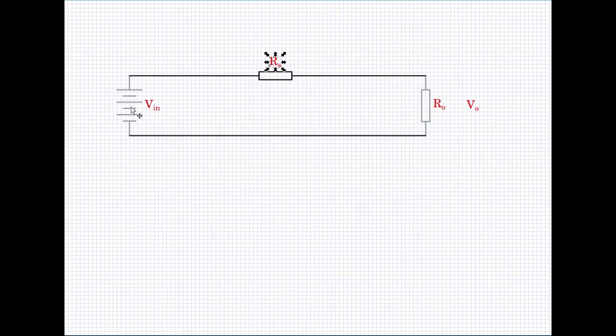Now let us say, for example, we have 48 volts at the input and we need 5 volts at the output here. The remaining 43 volts has to drop across this resistor. This would be the series drop resistor, and this is the typical concept that is used in almost all linear regulators. Now this resistor can be a varying resistor so that you can achieve regulation. As the input voltage varies, you vary this resistor such that the output is at a regulated level, whether 5 volts or 12 volts or whatever voltage that you have set.